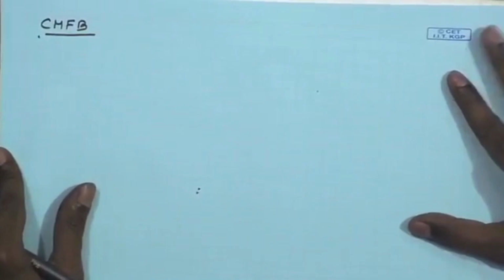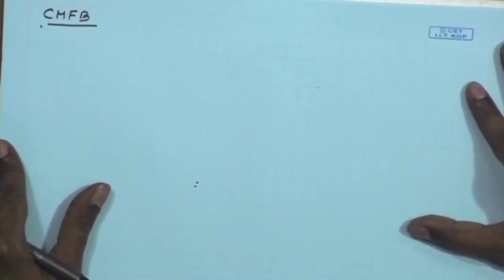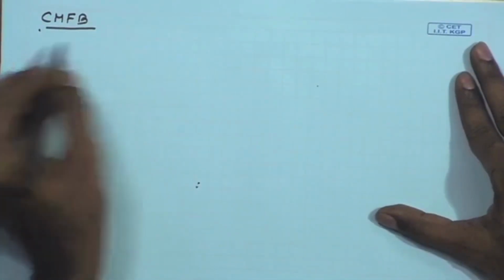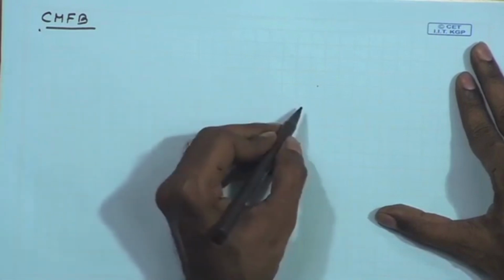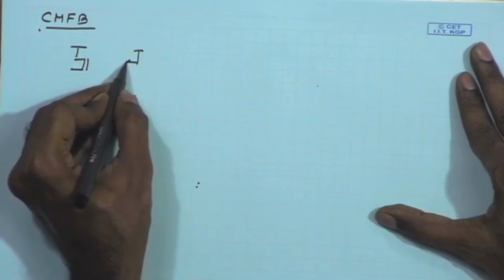where we take the advantage of a differential amplifier with current mirror load, which has a well defined DC bias point. So, let us visit our differential amplifier with current mirror load in order to be used as a common mode feedback unit.